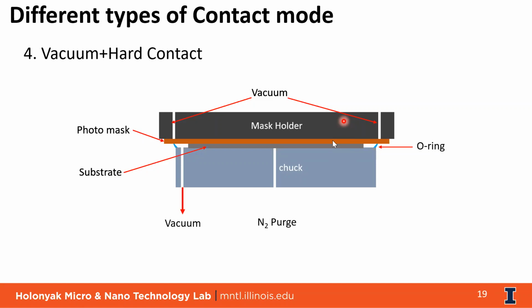Let's return to Piranha. If you use Piranha to clean a chrome mask, how do you manage its aggression on removing the chrome?